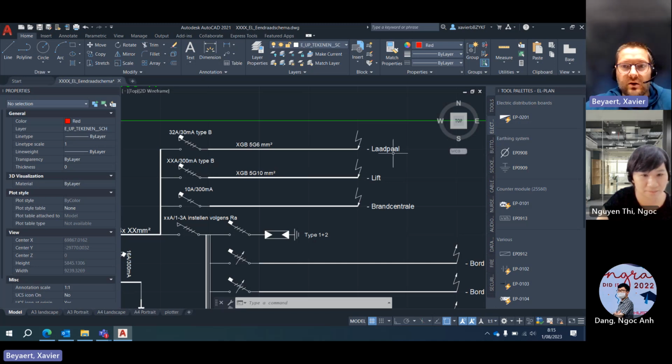So for a loading and charging station for a car, for example, or for an elevator, those have frequency drives. Those frequency drives cause a DC current in your AC current. So they have a DC component in your system. That DC component is a distortion of your system, so that can be a problem for your type A differential unit.